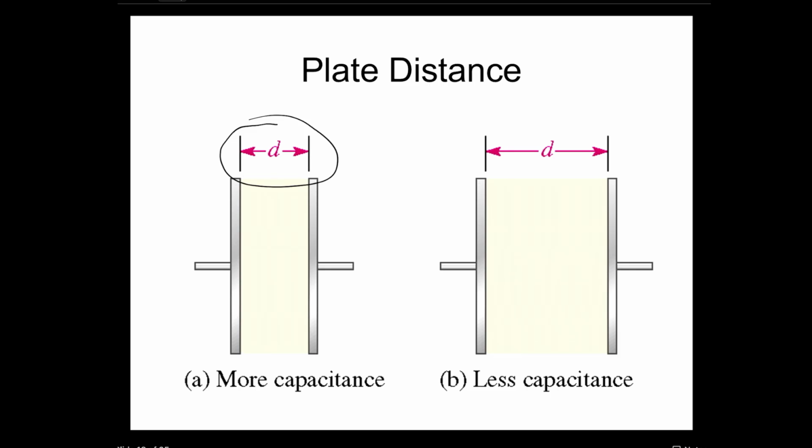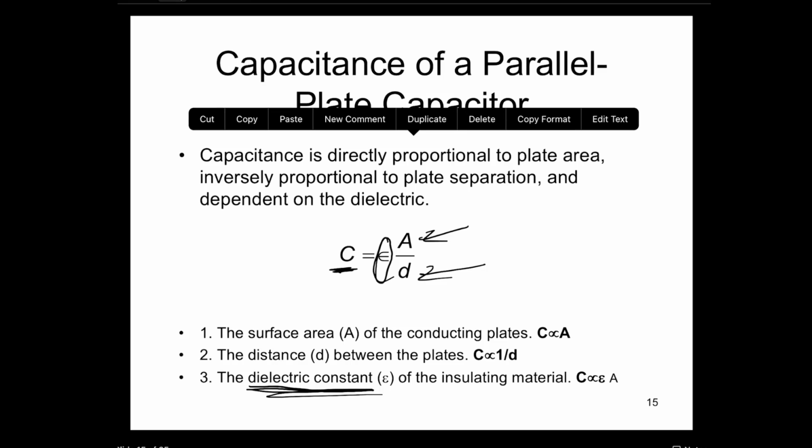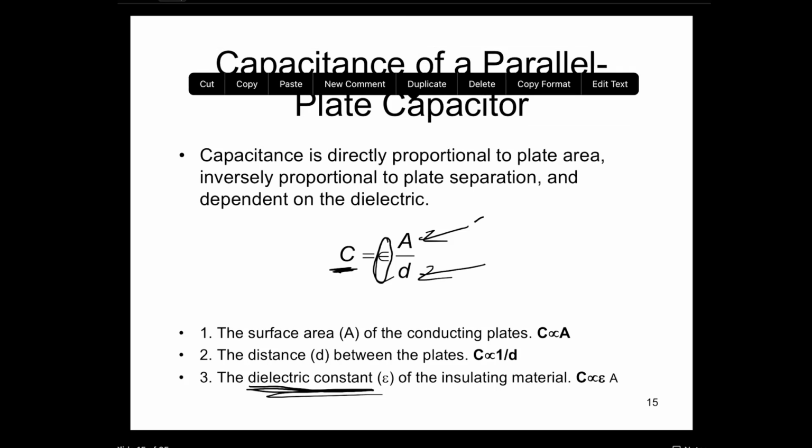So really, what are we talking about when we look at this? Well, we're looking at the same idea as what we talked about when we talked about conductors or inductors. We can just use it to have a better practical understanding of capacitors. As an example, what would happen if we doubled the plate area? Well, doubling the plate area would double the capacitance because we'd be putting a 2 times value into this equation, right? So we'd be putting a 2 times value here.